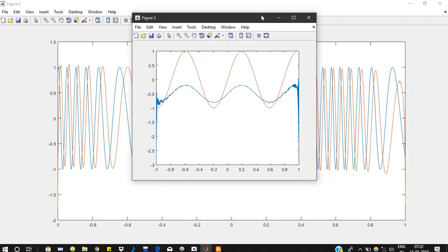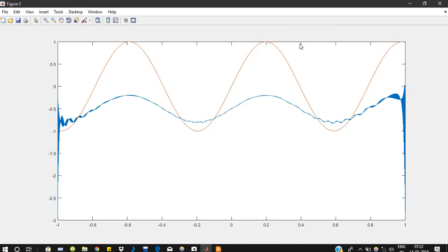So if you perform FM demodulation using the method I have mentioned, differentiating and unwrapping the angle of the complex number estimated from your signal, you can see my orange colored signal is my message signal, while the blue colored one is the one I have demodulated using the Hilbert transform. As you can see, it also closely follows your message signal, except for certain computation errors that you cannot avoid. These glitches you can see over here can be thought of as floating point errors.